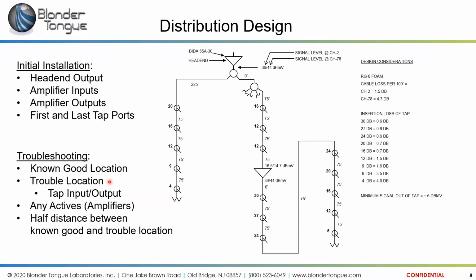And if those numbers, those measurements fall within about a decibel or so of the calculated measurements, I would say the system is pretty tight and in good shape as far as the health of the system. And you should not need to take measurements beyond that.